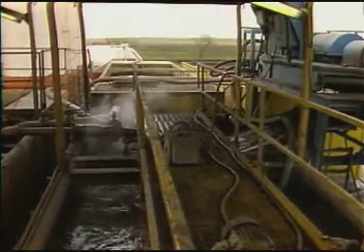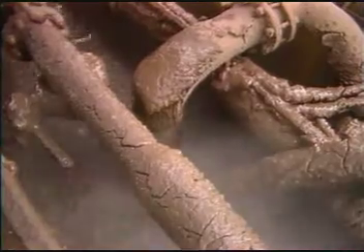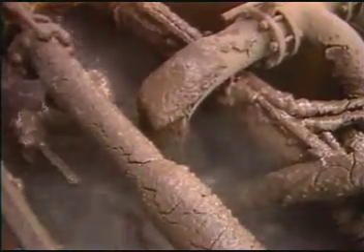Another factor contributing to the hostility of the subsurface environment is temperature, which also increases with depth, usually about 2 degrees Fahrenheit per 100 feet, or 3.6 degrees centigrade per 100 meters. High temperatures require expensive, specially formulated drilling fluids and can seriously affect the performance of downhole equipment, weakening metal parts and causing electronics to malfunction.